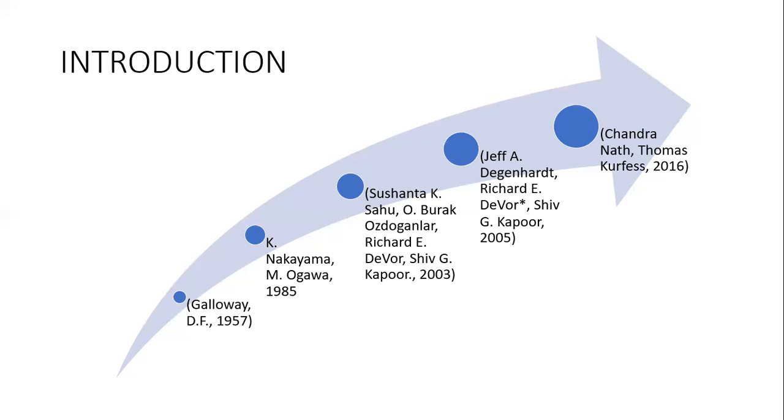However, in Makoto Ogawa's research, the effect of comparing the number of splitting nicks on the drilling process has not been studied. The purpose of this research is to make splitting nicks on the cutting lips of the twist drill and to vary the number. The success rate of cutting lips modification from several configurations of the number of splitting nicks on the twist drill is measured by determining the machine spindle load during the drilling process, chip morphology, and surface roughness of the drilling results.